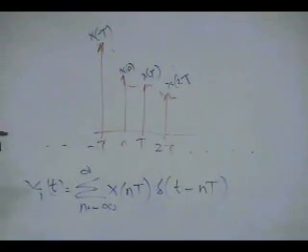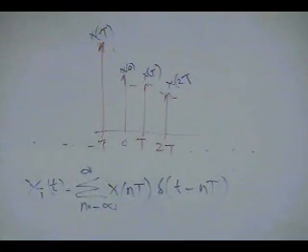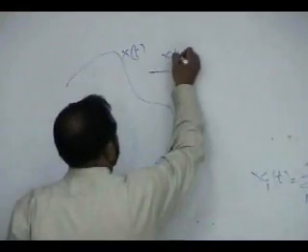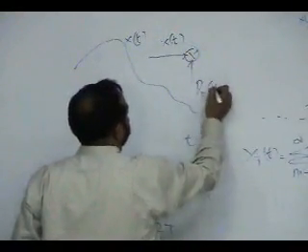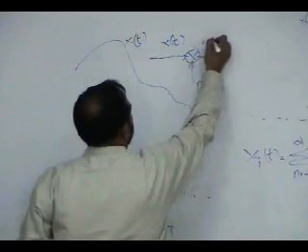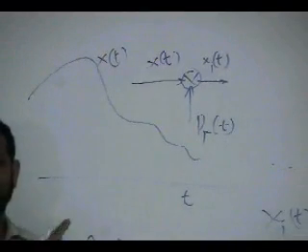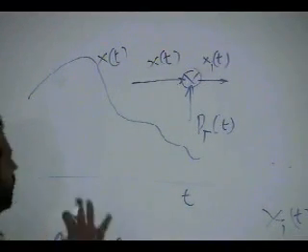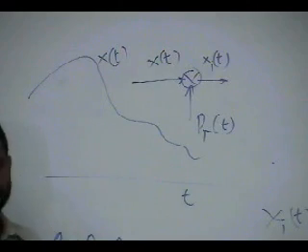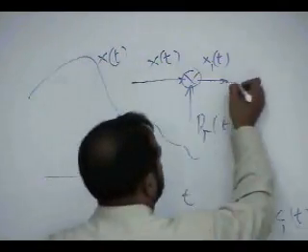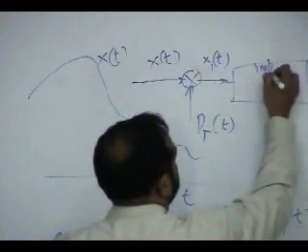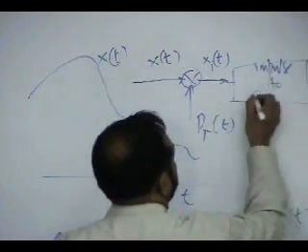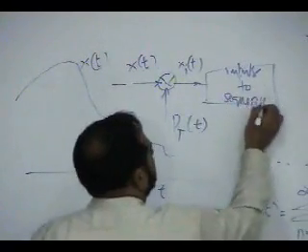So you get impulses. It says, okay, what you do is you take a signal x of t multiplied with a train of impulses. Then what you get is a train of impulses, with amplitude equal to the amplitude of the signal at the location of the impulses. Then it says now discretize, and discretization means you convert impulses to a sequence.